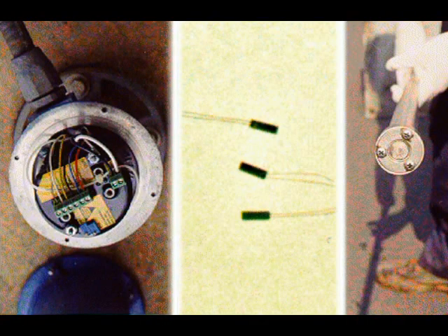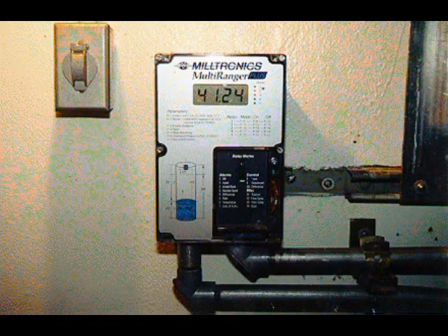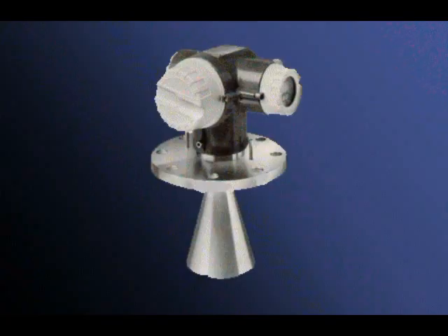Strain gauges are a second type of control system currently in use. A silicon diaphragm is doped to produce a strain gauge bridge. Pressure to one side of the diaphragm causes a resistive imbalance in the bridge. This change is sensed by an electronic network, which produces a DC signal in the range of 4 to 20 milliamps, proportional to the applied pressure. This signal is applied to a controller that has selectable parameters used to open and close relays and thereby control the pumps. A third type of control is the microwave.